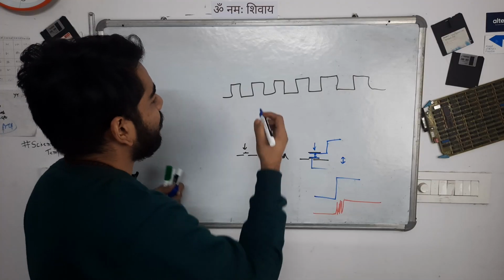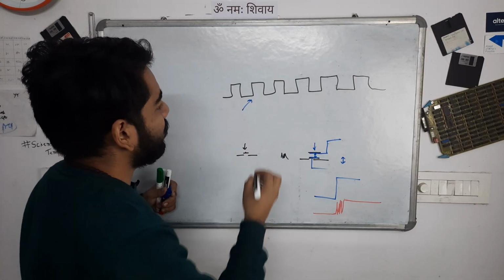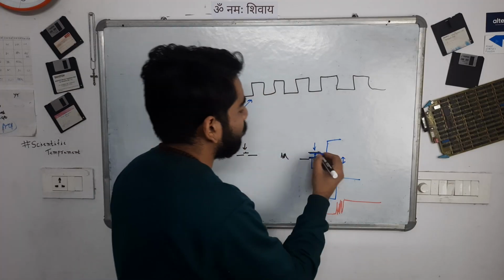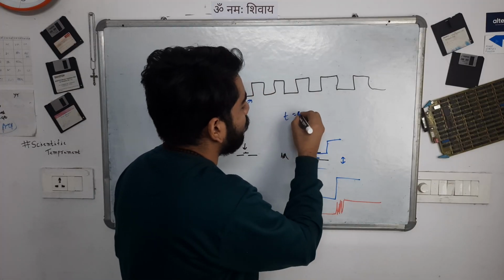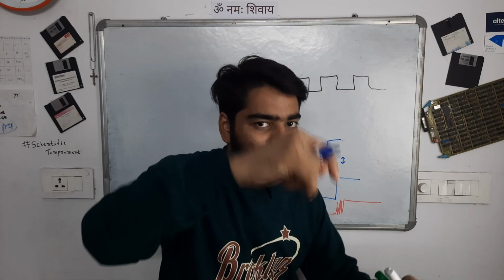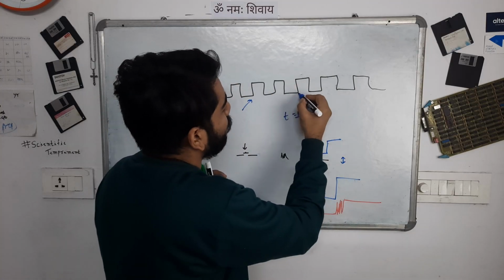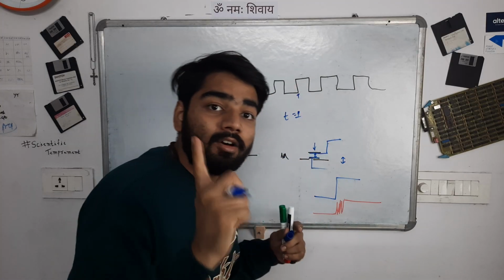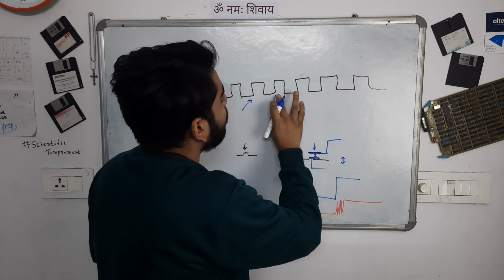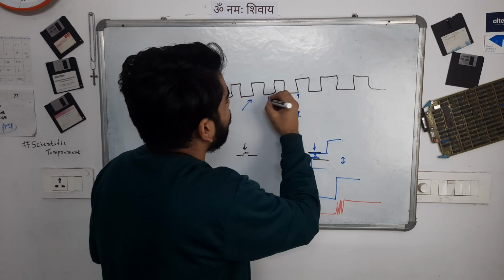The next reason is the fast clock. Because of the fast clock, this is sampling very fast. Let's see what is going to happen. When I push the button, t is equal to 1, but since I'm pushing it with my finger, my finger is not fast enough to lift off the button before the next clock edge. Let's say I push the button over here.